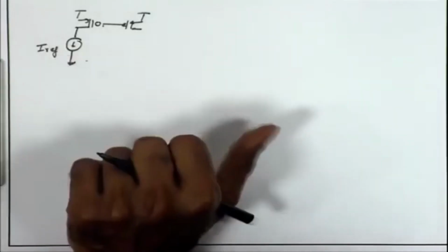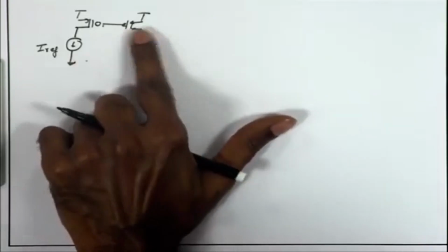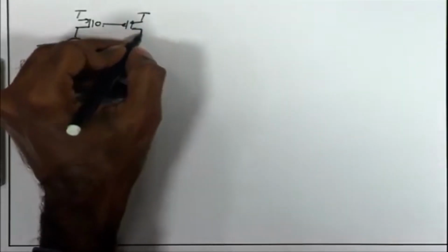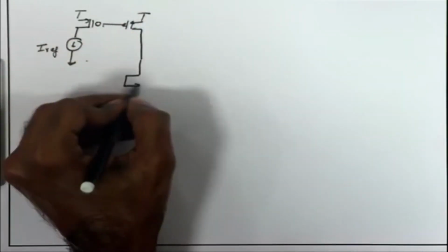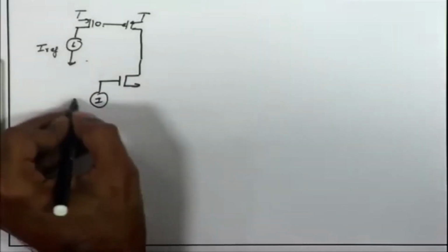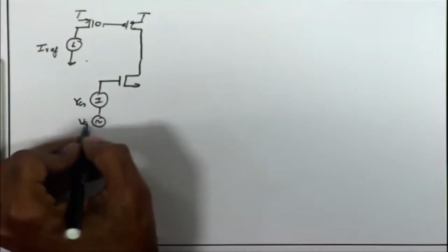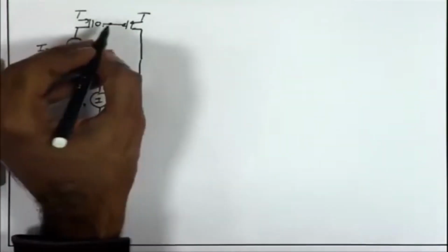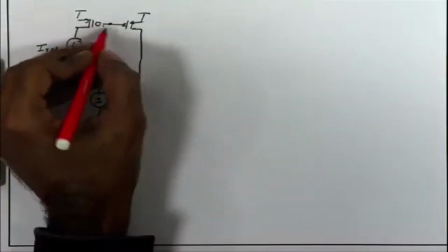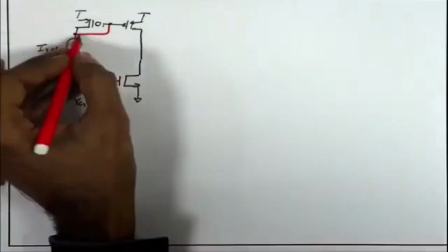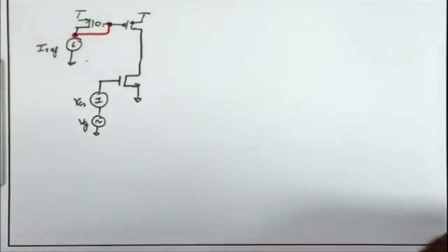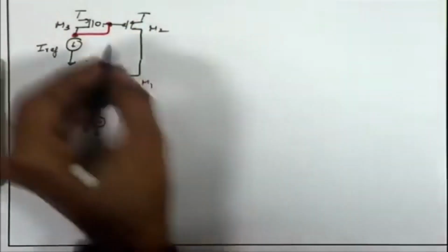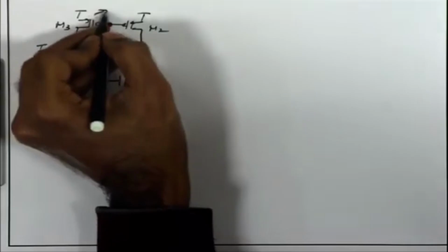And using this reference current, I can form a current source which is going to provide the bias current to my NMOS transistor. So, this is once again my earlier device. I have the capital Vg, on top of that small Vg, and here I am trying to form a current mirror. So, this is a diode connected MOSFET. If I call this M1, M2 and M3, M3 is diode connected, drain and gate are shorted.